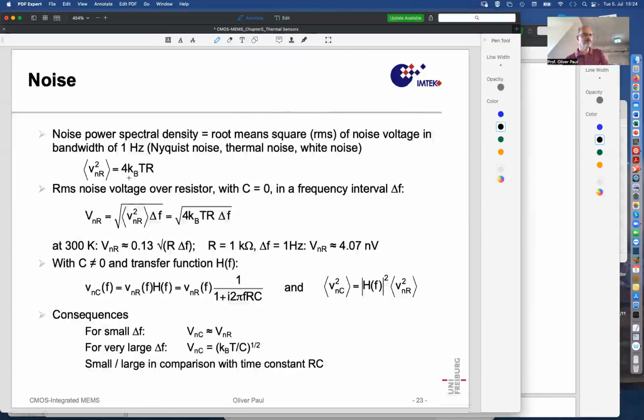And if you now let that 1 hertz become 10 hertz or 100 hertz or 1000 hertz, you're adding noise contributions from different pieces of 1 hertz. And that noise is again independent. The noise at 1 hertz is independent of the noise produced at 2 hertz and so on. Those contributions are going to add up incoherently, which means that one can add the squares of the contributions.